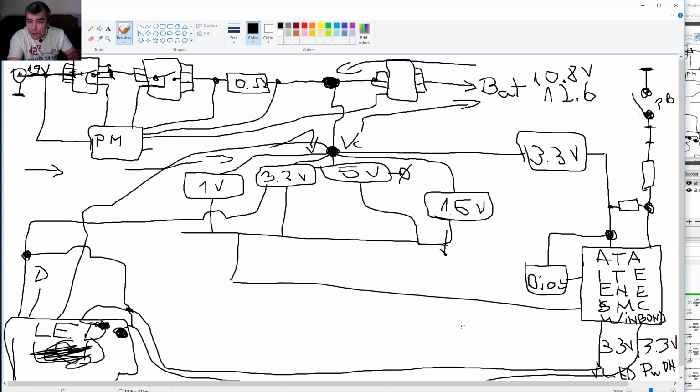Also, when you have a graphic issue, the board will fail the test and the screen will have no light. So when you have no light, you probably have a graphic problem, or you have no memory. The board will fail the test, and the screen will not come on. That's a sign. If you have light, that means the board passed the test.